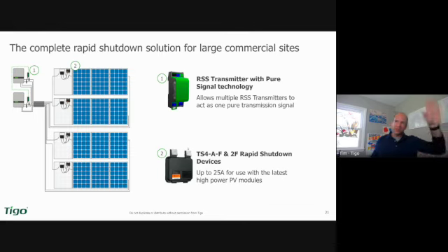So we talked about the mesh network and the tap and the CCA. That's everything that has monitoring. If you're using the F, which is just rapid shutdown, what that does is that it uses what's called this RSS transmitter and what's called a core. So if you can see, it's this little donut looking thing below it. To quickly describe it, basically what this does is think of this transmitter as monitoring the grid, and it sends out a keep alive signal or a heartbeat out into the system. And it's basically saying, yep, everything's good. Stay alive, stay on, good, good, good.